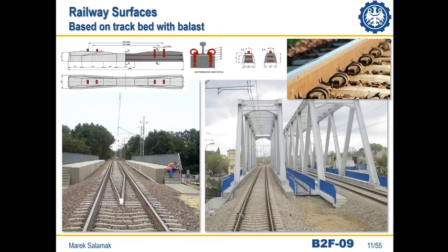Track bridges with ballast through and ballast bed are most commonly used on new bridges today. It allows ensuring similar comfort conditions for trains crossing the bridge to those which prevail on the route outside the bridge. There is also less noise and better vibration damping. Pretensioned railway sleepers are used for this.